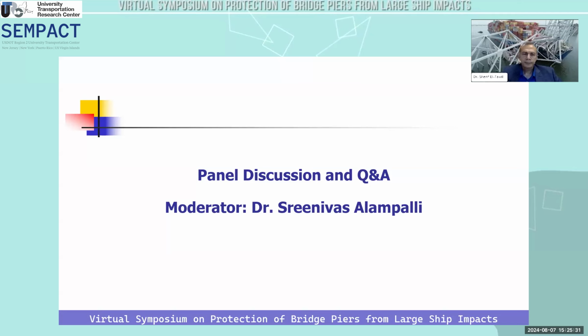One other comment I'd like to make. I didn't get into this today, but one of the benefits of using simplified modeling is it allows you to do probabilistic simulations in some cases, where you can probabilistically investigate the effect of different situations, whether that's impact angles, structural characteristics, soil conditions, or so forth. And having simplified methods facilitates things like Monte Carlo simulation, whereas relying solely on very complex models, it's much more difficult to achieve those kinds of simulations.